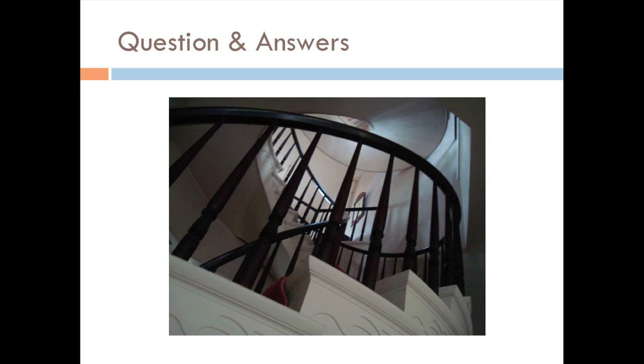But keeping water specifically out of the wall is a fight that's probably too difficult. It's better to work with it, to allow it to slowly escape on its own through wetting and drying cycles. If you had cement versus a pure lime or a hydraulic lime on a building, the water is not going to be able to get back out and pass through that Portland cement-based stucco or plaster application. It'll try, and it might get to the surface behind it, and then it would freeze and crack. If there's water vapor transmission, such as in a natural hydraulic lime or pure lime, it can pass through.